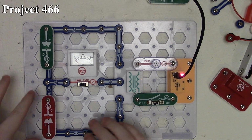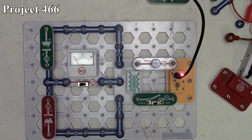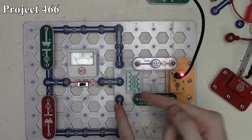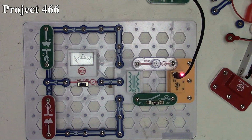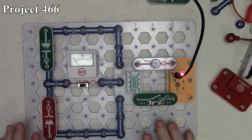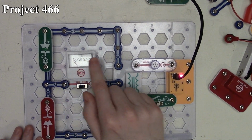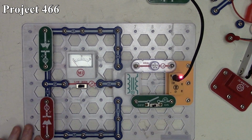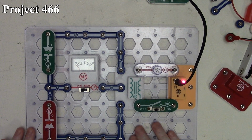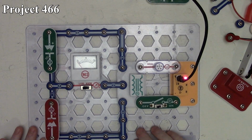So the way that the LEDs are configured here is the current is flowing in like this and then through the meter, as opposed to 358 where the current was coming out through the meter this way and then going through the LEDs. They would turn around. So this basically has the opposite effect of what Project 358 does. With Project 358, the meter deflects to the right because our current is going that direction. But in this project, the current is going in the opposite direction. So our meter will actually deflect to the left below the 0 point.